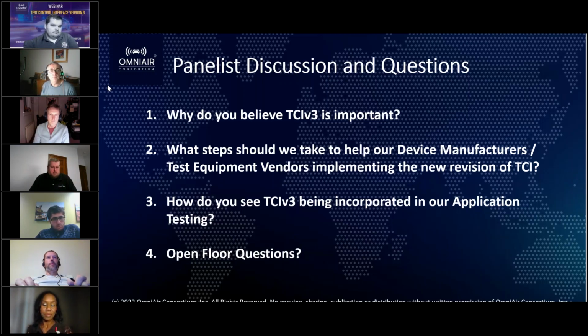I wanted also to mention that when we are talking about the XML file, we are usually talking about one chipset provider, but there are also other chipset providers. So if we do provide different V2X XML files with different radio configurations included, it might be a good idea to provide the radio configuration itself, at least in addition to the V2X XML file, so that everyone knows exactly not only from the name of the V2X XML file what is included, but also has a clear overview of the radio configuration itself.